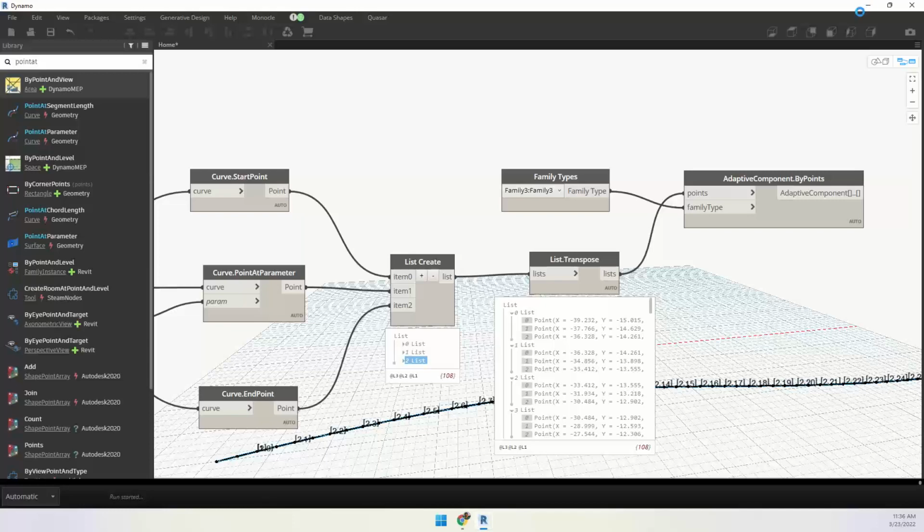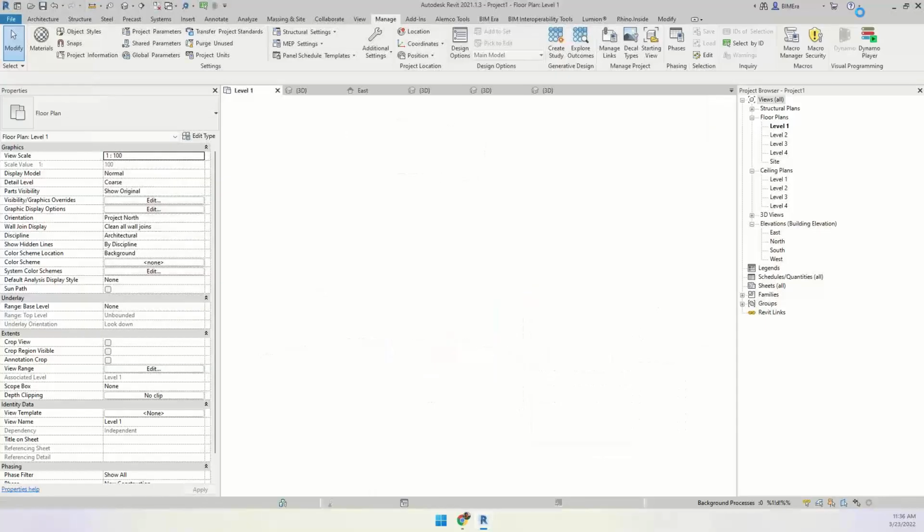Generally, when you're thinking about splitting that into segments, we will use only 2 points, like a 2-point family. But generally, when you're playing with any curve-based element, I do suggest you go with multiple points. At least you should start with 3 points.